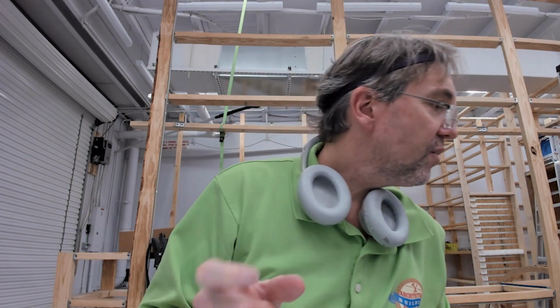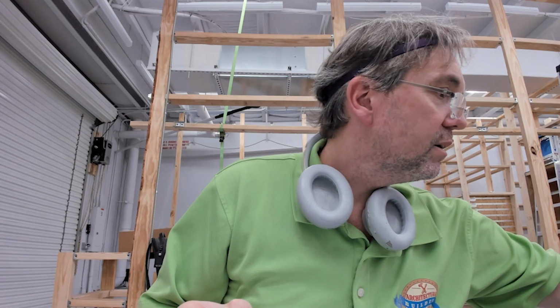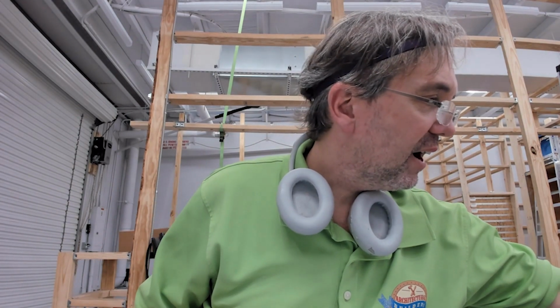So, they've got a 1/4 inch diameter. And the reason that I'm going with that is because I want to get 8 pieces of these ceiling tiles out of a single sheet. And I'm going to make a single profile pass to separate the two pieces because that edge doesn't matter. It's completely concealed. But as I look at what tools I have, a 1/4 inch end mill is going to work just fine.